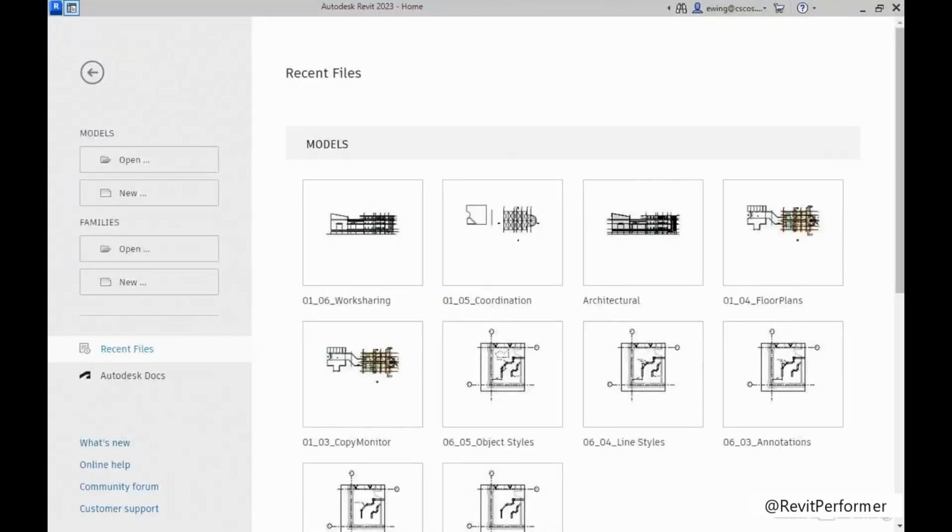One of the biggest reasons we use Revit is the fact that multiple people can work in the same model at the same time. The end of that statement is kind of misleading though. We're not actually in the same model. When Workshare is activated, that means there's a central model on your server that you're making a copy of. That copy goes into your local documents folder. That copy has a link back to the central model on your server. When you save your model, it synchronizes the changes back to the central model.